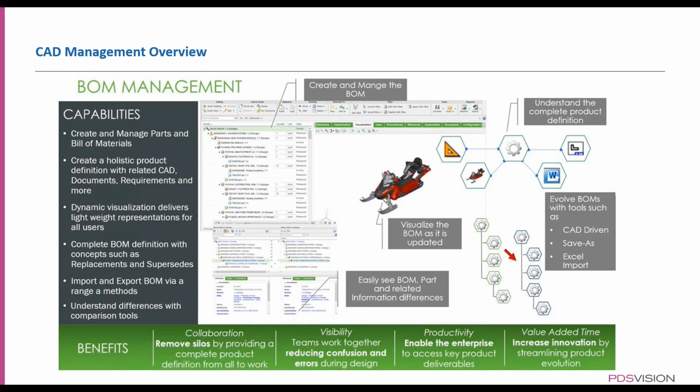So I can go in and export a BOM to a PDF output, or export the BOM to an Excel. In that sense, I don't have to look at the drawing and try to deduce and create my own bill of materials manually by typing it out in Excel. It's easy to make mistakes and errors there. I can just export the BOM as is, with the columns that I need, to an Excel, and if I want, I can further manipulate it in the Excel output file.